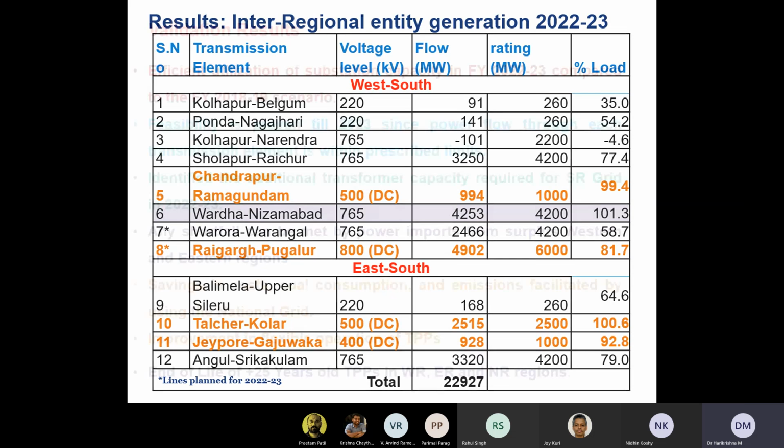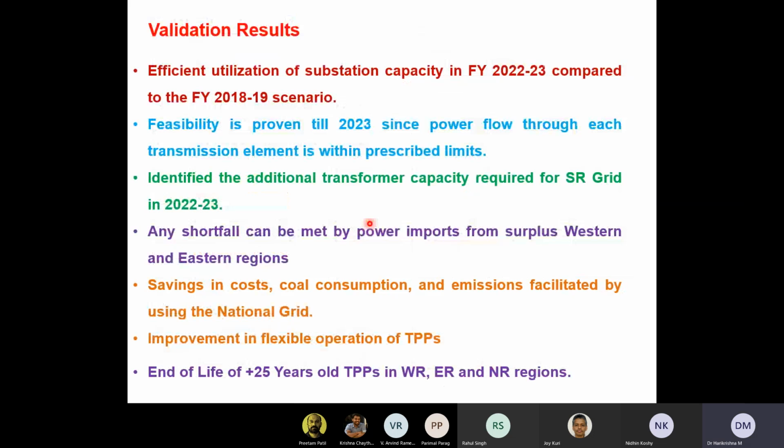We found that, in comparison to the 2018-19 scenario, the system is able to improve the performance with the proposed analysis. Also, several substations were found to be operating at their maximum capacity or may not be able to feed the power in the absence of a particular backup component or element, which I can say is under an N-1 contingency scenario; it may provide some issues.